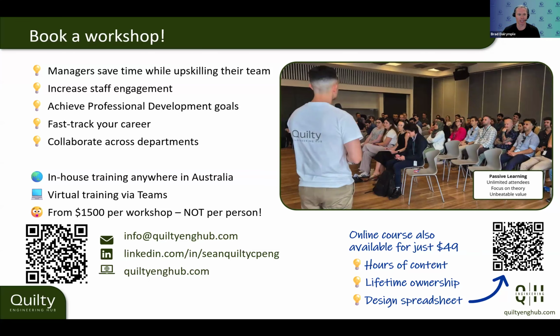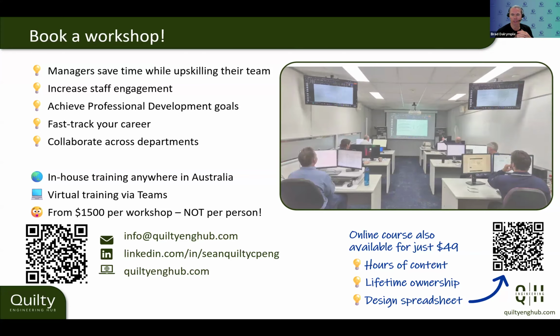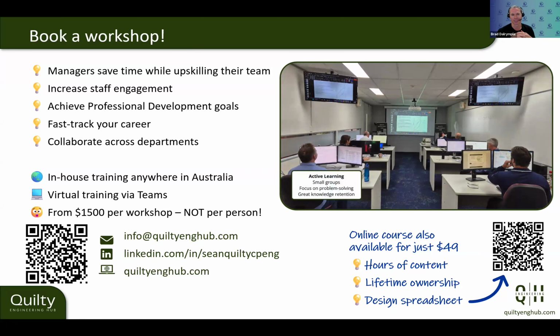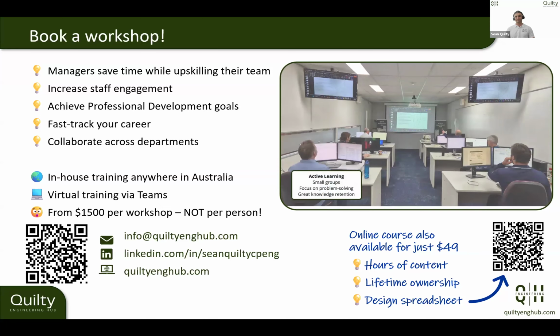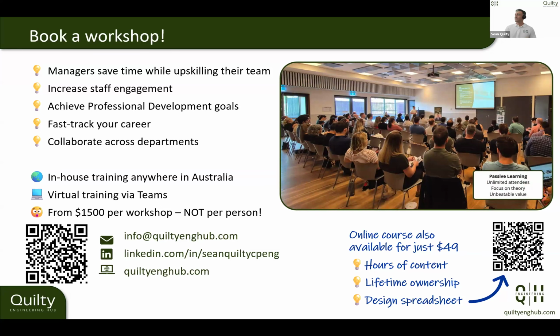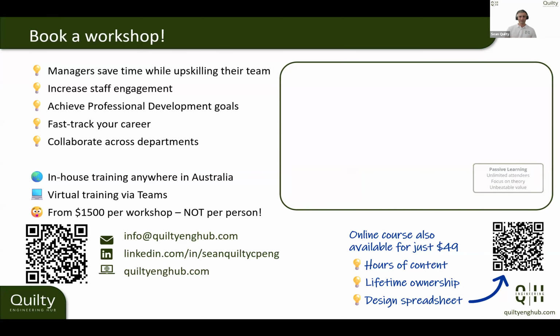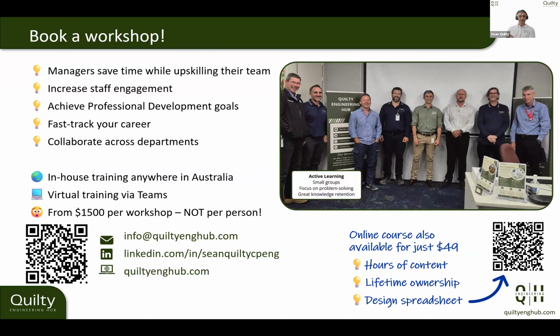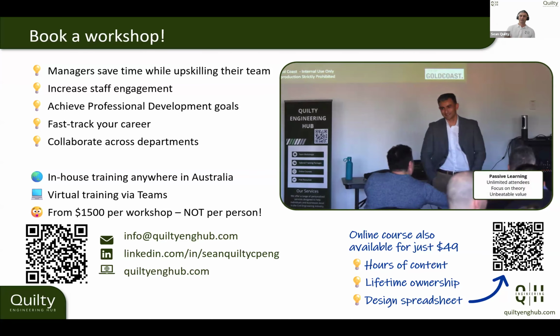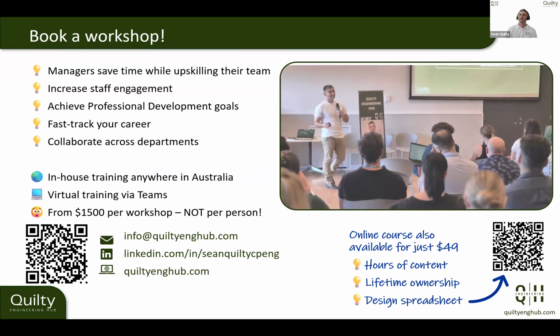But Justin Sweet from Griffith University and Nathan asks, can you create your own coefficients for Mannings? Yes, you can create your own Mannings value. I'm trying to think of some examples. I think it is Strickler's equation? There's an equation for rocked channels, depending on the rock size and maybe even shape, the uniformity and a few things. You've got an equation that will give you an N value, 0.063 or whatever it happens to be, based on the material that you're using. There's definitely one for rock lined channels.